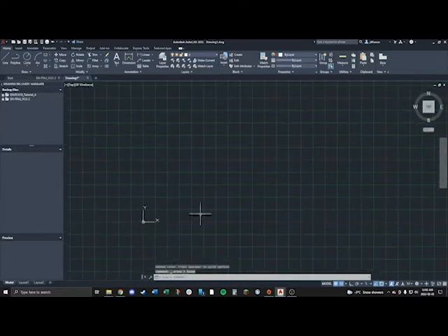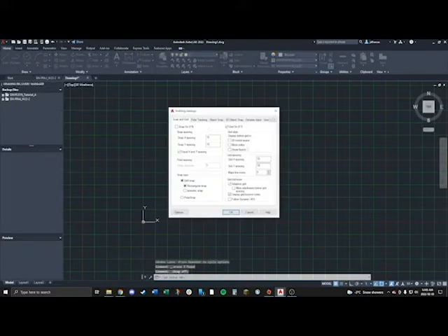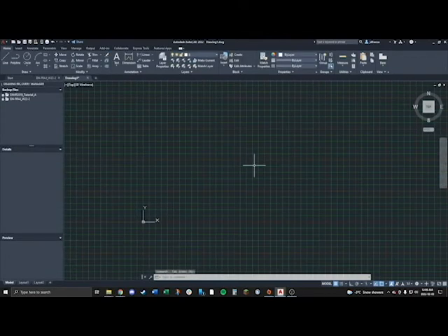So we're back here. In the second part, we have to use snap grid off. Typically, this is how I like to do drawings. Also, to change your snap settings, you go in here. This will change your snap settings as well as just your grid spacing. So I want a major line every 5, and I'm actually going to put this to 5 just to make it a little bit more accurate, a little bit easier to see. So for the next part, we're going to go over what to do when snap grid's off.